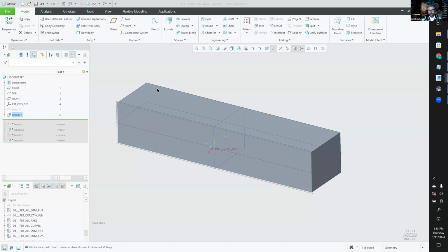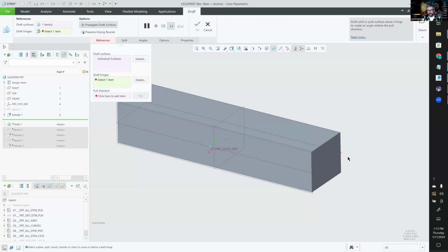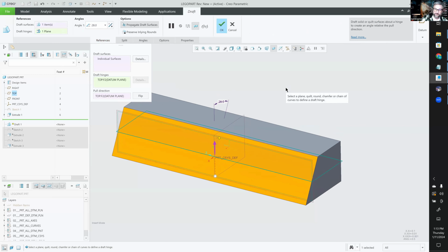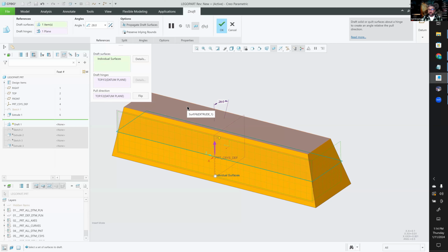Right, so there's my draft, and then I quickly pick what I want to pivot the draft about, and then preview. By the way, people love SolidWorks, but SolidWorks has never had a preview until 2024. Pretty wild how they get away with that. So sometimes when you get your draft and you're trying to figure out these tools on your own, like engineers do, you don't realize that you're on one of these or not. So be really mindful about which one you're grabbing. So I want to grab these other two.